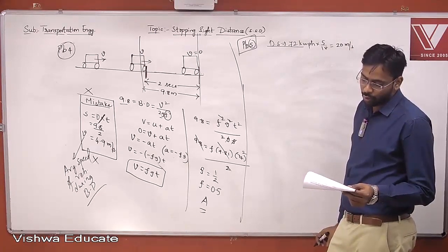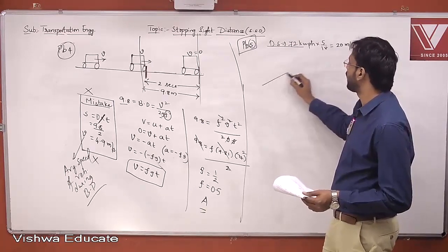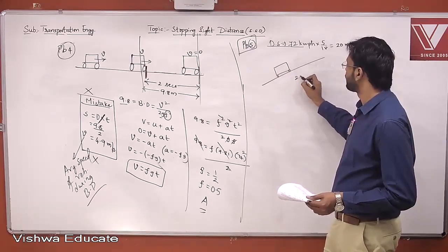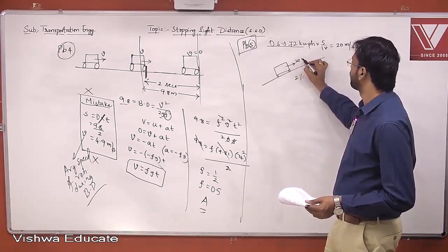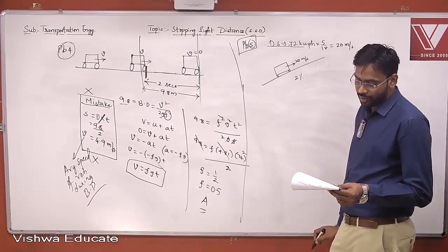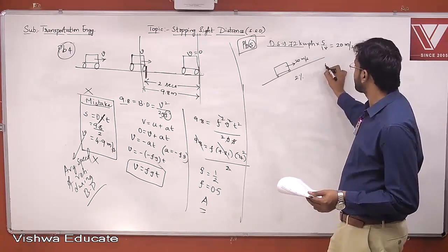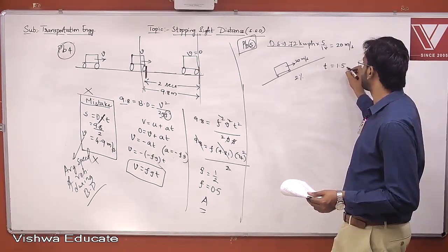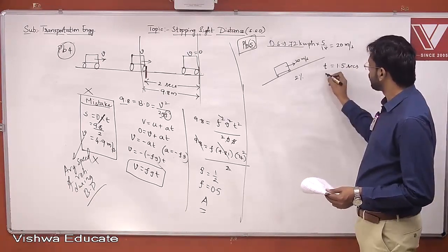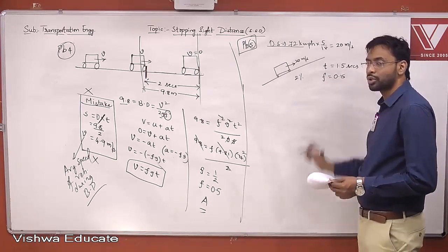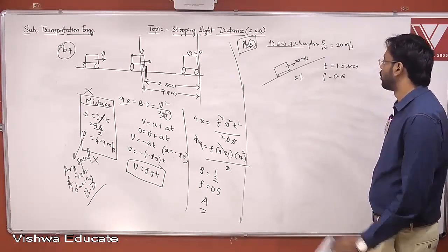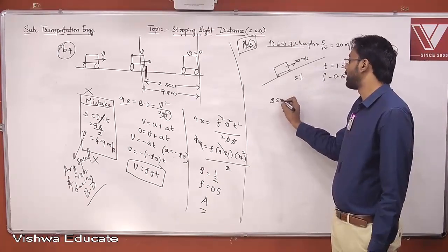Okay, it is moving on a road having a 2% upward gradient. So it is moving on an upward gradient. Gradient is 2%. The driver applies the brake when he sees an obstruction. Okay, and the reaction time of the driver is 1.5 seconds. Assuming f is equal to 0.15, so the coefficient of longitudinal friction is given as 0.15. Calculate the distance traveled by the car before it stops. So he wants us to calculate the stopping sight distance.